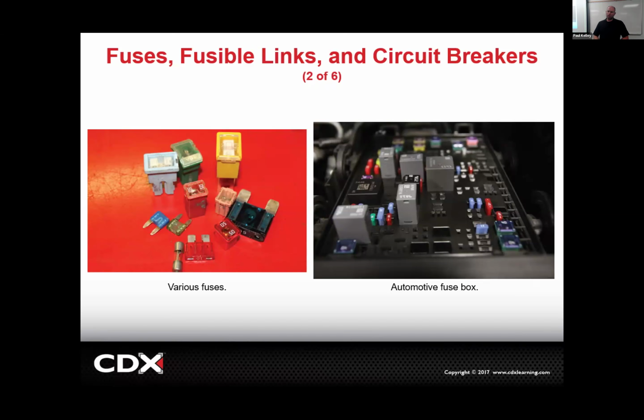Now that brings up another point that we won't solve today, but I'll make sure you understand. If the fuse blew, something caused the fuse to blow. So let's say the most common, where you plug your cell phone charger into a little power outlet. It used to be the cigarette lighter. You plug that in, and if periodically it blows the fuse, the problem could be on the vehicle side. But what's pretty common with those cell phone chargers is they have some wire like this, and the wire flexes, and you put it in your pocket and it flexes, and eventually inside it might break a little bit and it could short out.